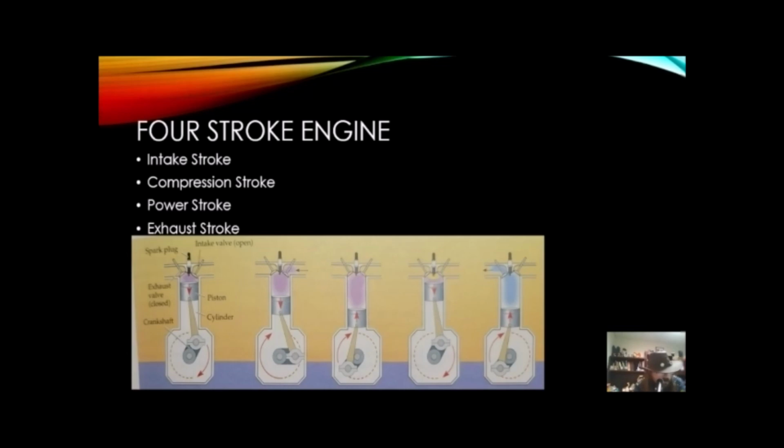The first thing, the key turns ignition that allows the battery to give the motor energy to start cranking. And from there, the 4-stroke engine works. It's called a 4-stroke engine because to complete a cycle, it has a downstroke followed by upstroke and then a downstroke and then upstroke to get back to the original point. The first stroke is the intake stroke, where we have the far left. The chamber is essentially empty. There's just a little bit leftover gas. The downstroke allows this chamber to expand to allow gas in, at which point the valve allows the fuel air mixture in.